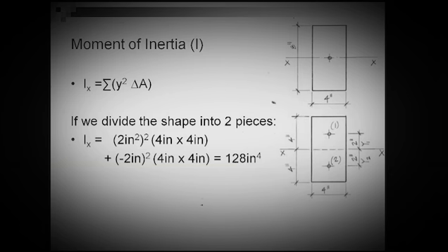Now, what is the distance from my neutral axis to the center of the first segment? It's going to be 2 inches. I'll tell you why, that's a very good question. If you kept it as 1 segment, the first iteration on the equation, it would be 0. Because if I kept it just at 1, I would be asking you what is the distance between the neutral axis and the center of this rectangle. That distance y would be 0, so the moment of inertia would be 0. That's the first reading based on this division, where you don't divide it into anything.